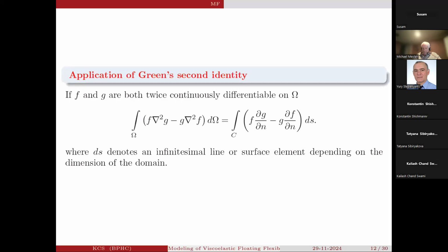Now, proceeding with the help of Green's second identity, we are basically using the boundary element method here. If we have the boundary value problem with the boundary conditions we have already described, and we have the fundamental solution, we can apply Green's second identity to formulate the boundary integral, which can be discretized into a boundary integral equation, where we will find some unknowns on the boundary.